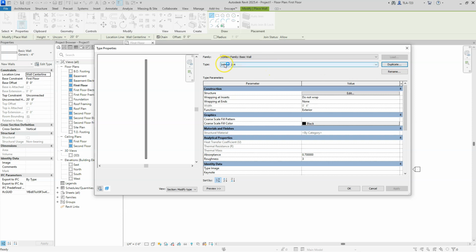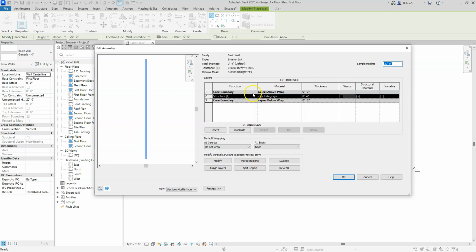We named it something, but now we have to go through and set it up to where it actually is that thing. So we're going to click on Edit, and you can see that the structure of this wall is nothing's really defined except for the function. So we have a thickness of 4 inches, which we may know already that that's not going to work, because if it's a 2x4, it's actually only 3.5 inches. So we're going to build this thing 3.5 inches thick.